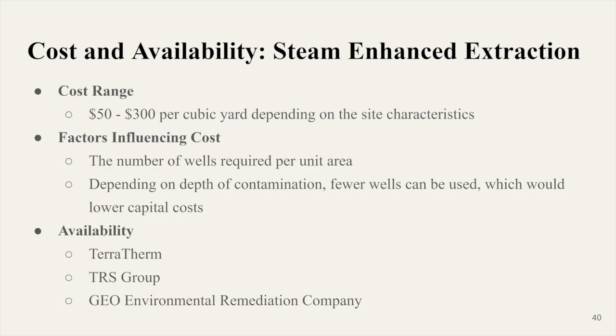Shallow contamination requires closer well placement and lower operating pressures to prevent soil fracturing. Deeper contamination requires farther well spacing and higher operating pressures. These differences in contamination depth show that fewer wells could be used depending on site geology, which would lower capital costs.